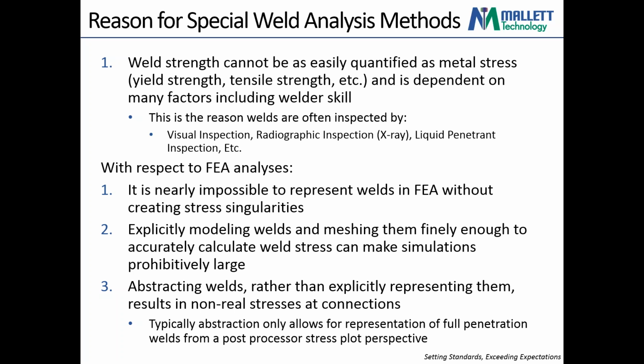So with respect to FEA analysis, it's pretty much impossible to represent welds without creating stress singularities. There's almost always a right angle or a hard termination when welds are modeled. And so what this means is if we're looking at welds on a stress plot, usually the stress results are masked by the presence of these singularities.